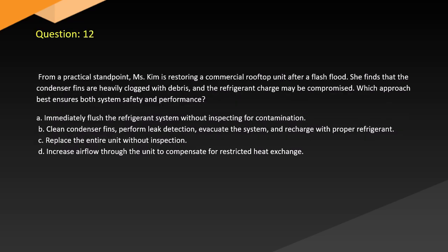Question 12. From a practical standpoint, Kim is restoring a commercial rooftop unit after a flash flood. She finds that the condenser fins are heavily clogged with debris and the refrigerant charge may be compromised. Which approach best ensures both system safety and performance? A. Immediately flush the refrigerant system without inspecting for contamination. B. Clean condenser fins, perform leak detection, evacuate the system, and recharge with proper refrigerant. C. Replace the entire unit without inspection. D. Increase airflow through the unit to compensate for restricted heat exchange.